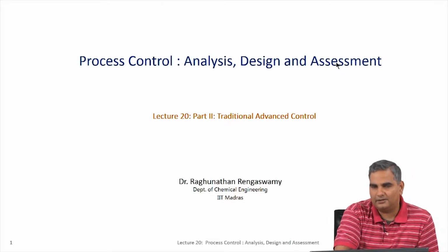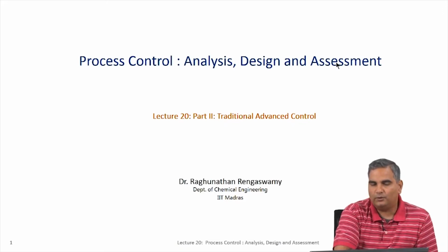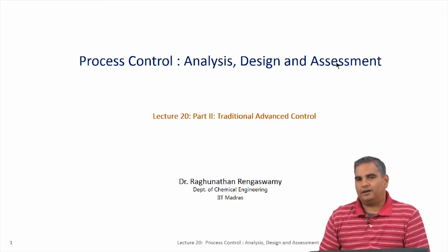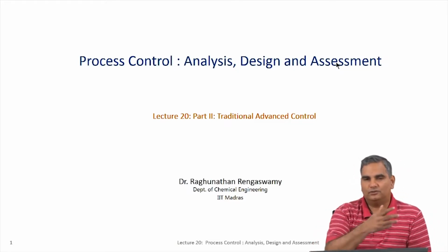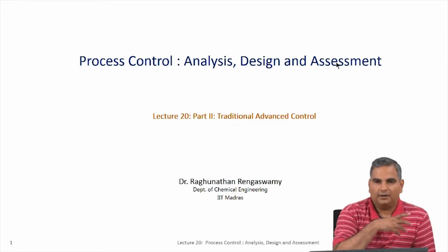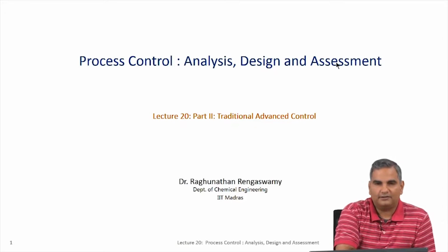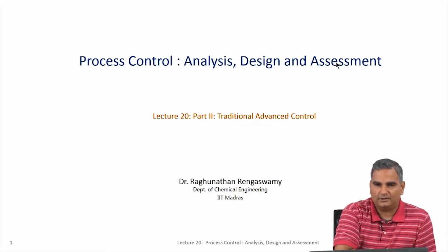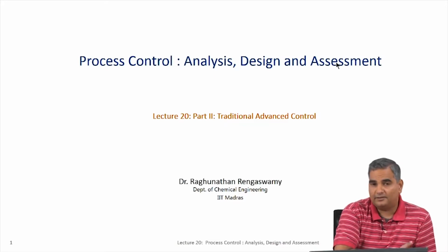Basically what this essentially means is that somehow you have to take care of this, and that somehow is in modifying our expectation for what G desired can be. So, till now we have never put any constraints on G desired. We said you choose any G desired you want, but now we will have to start enforcing constraints on G desired, so that we do not design a controller that becomes unstable. So, that is a key idea.